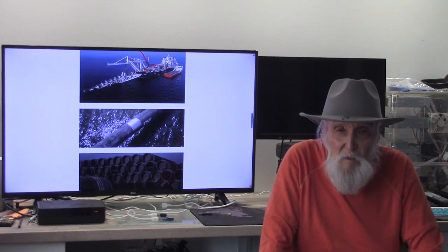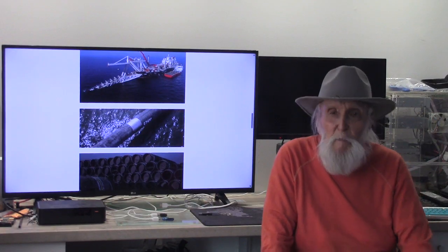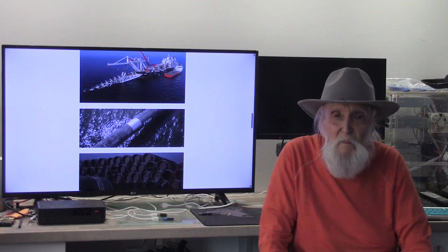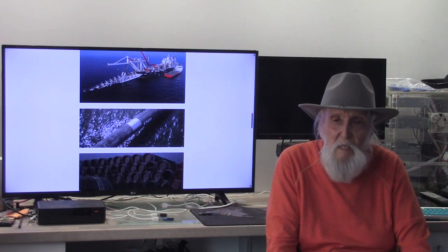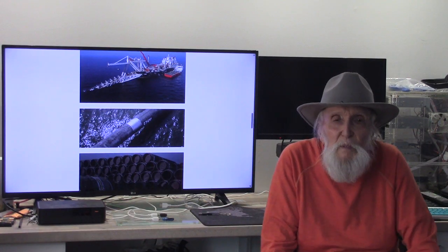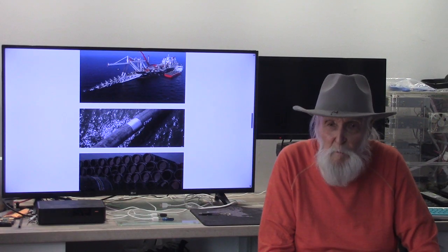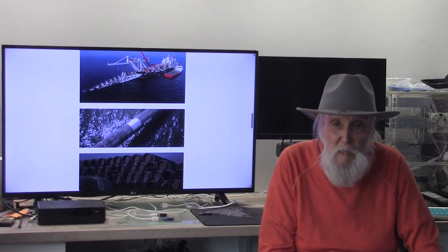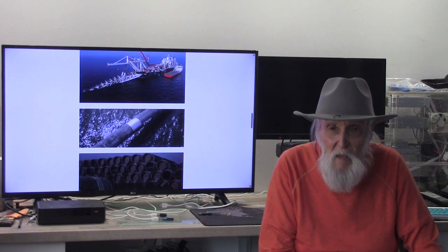Later, as corrosion engineer for Shell BP Nigeria, I investigated repeated leaks on flow lines through direct current and potential analysis. I proved the cause to be accelerated corrosion from stray current discharge.